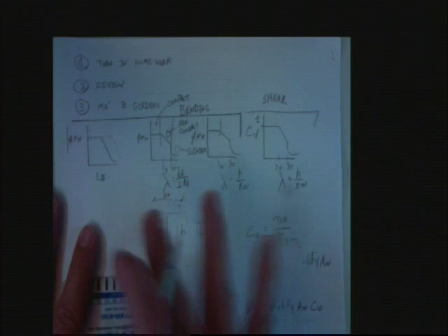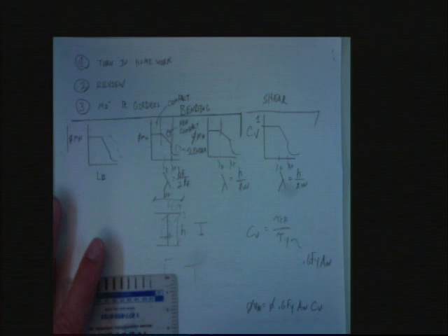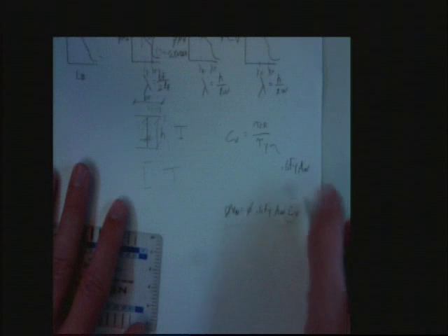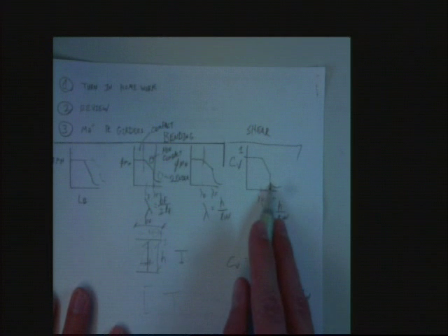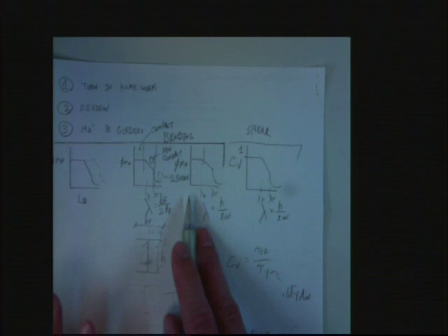Okay. So we've talked about these different zones. We've kind of reviewed these different snail charts. We've talked about what's important about them, what's kind of strange, what's not strange. And the last thing I meant to go back to here was when I get above gamma sub p, all I'm doing is reducing my shear linearly. And we can reduce some shear linearly, and that's not that big of a deal. We showed previously that we had like 80% more shear than we needed on that example problem. You can live in this zone. It's just when you start to drop down here, the bottom drops out real quick. And you really start to impact your moment as well, a lot. Something to keep track of.